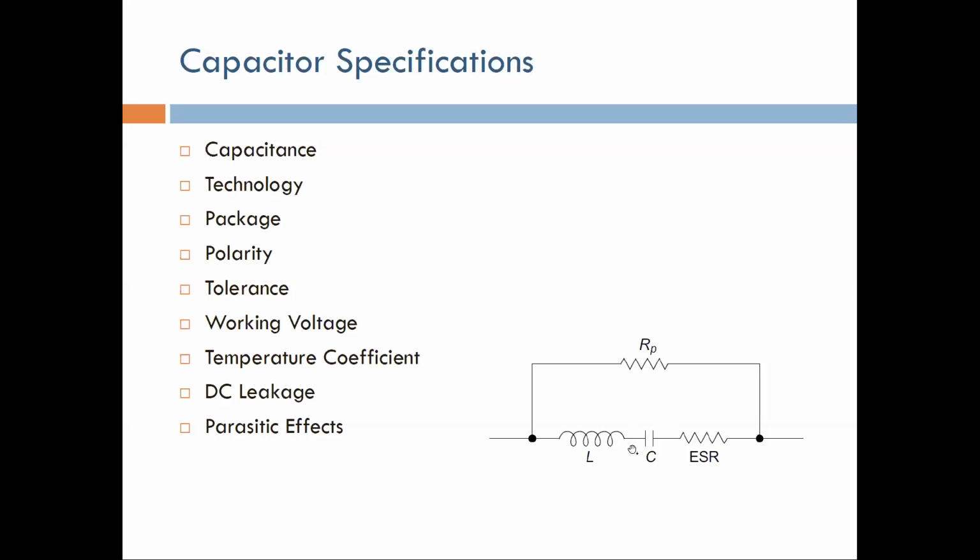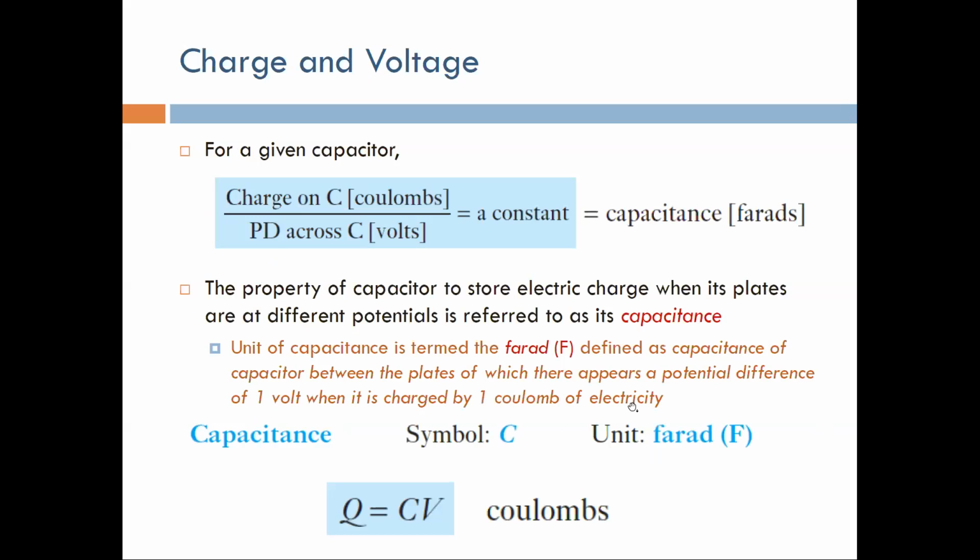Sometimes you have of course your basic capacitance. Sometimes you have a resistance from the leads themselves. And sometimes you have an inductance because also of the kind of leads that you're using. So basically, it has a model that looks like this. But usually, if you work close to DC with a very low frequency, you see mostly the capacitance. Okay, but just be informed that there might be some other parasitic effects or side effects to the capacitance that you have to take care of or consider.